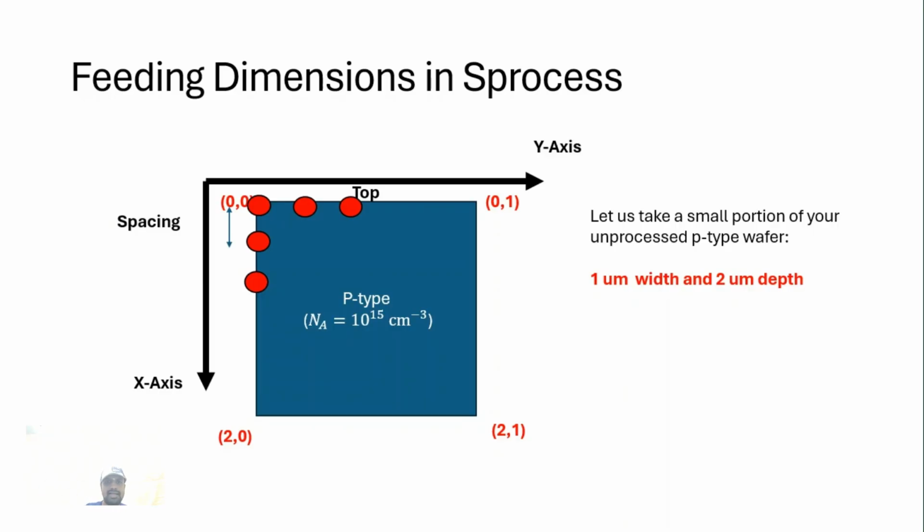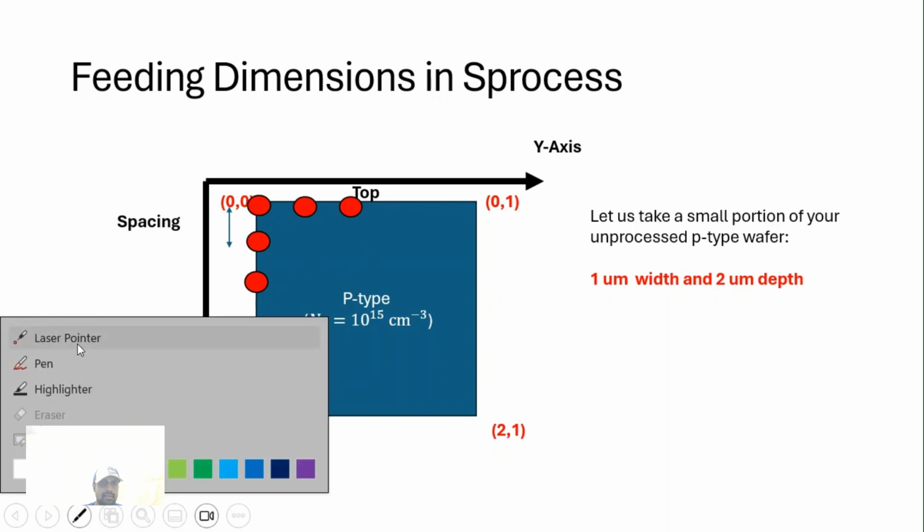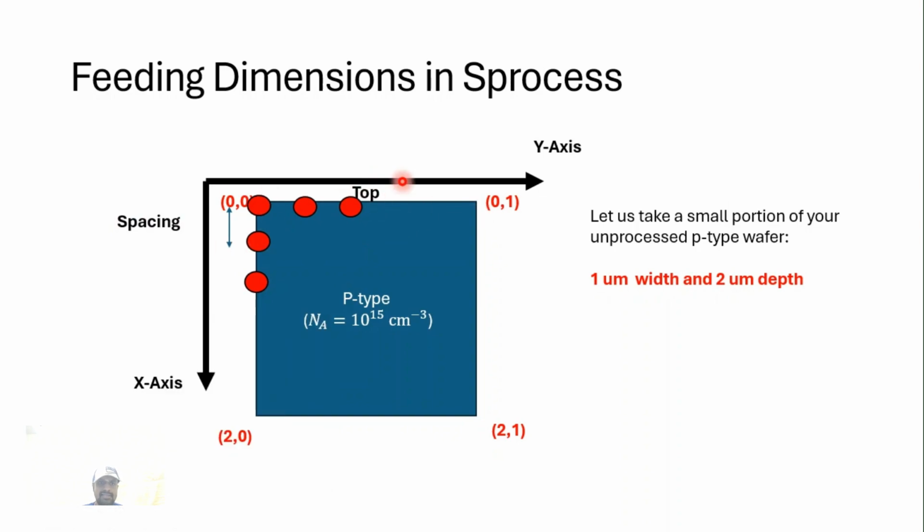It's a small additional thing. So for x equal to 0, which is the top surface? This is the top surface, right? So let us give tag as top here. And this is the bottom surface. So let us give tag as bottom here. Okay. So when x equal to 0, that is top. The tag is top. For this one, the tag is bottom. Similarly, this one is left. This is right. Okay. Tags are very useful. We'll be referring to them later. Just a label for the surface. Okay. So these are the things you're going to now program in the process commands. Let's do it.